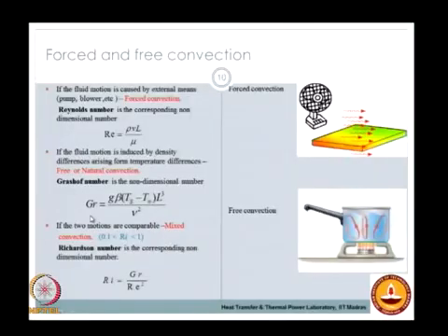So this is called free convection or natural convection, and we cannot use the concept of Reynolds number here because essentially we do not push the air by means of an external pumping device. So here we define another non-dimensional number to characterize the strength of natural convection, the Grashof number. The Grashof number is the ratio of the buoyancy force to the viscous force.